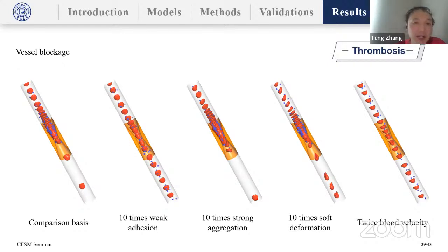Okay, thank you. Related to the discussion about the mesh and the particle-based method, I'm not an expert on this, but I think with the mesh method, you need to take care of the unused volume, right? For the particle method, you only need to discretize your real geometry. For the mesh, like lattice Boltzmann or finite volume, you need to discretize the whole domain. Right? Yes, correct. Okay, thank you.